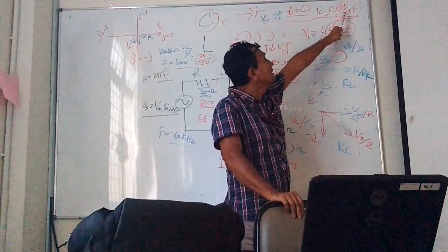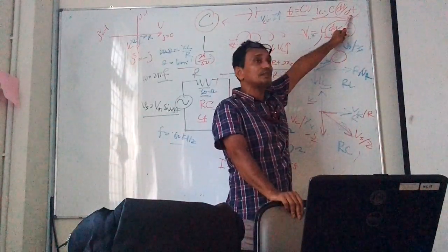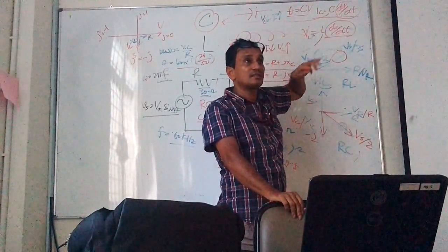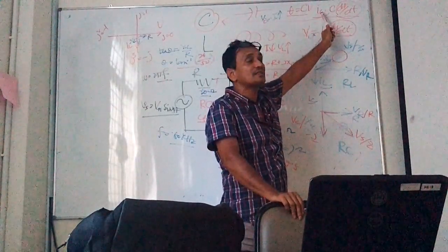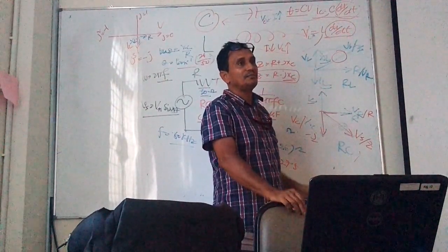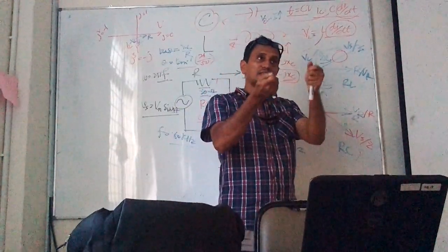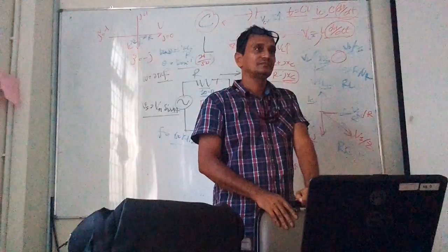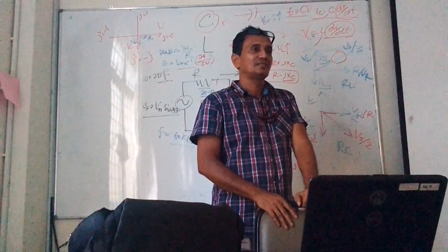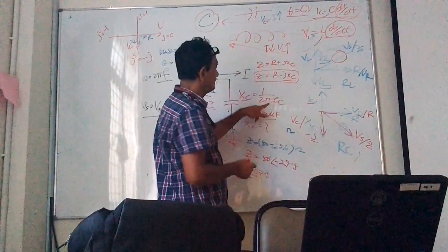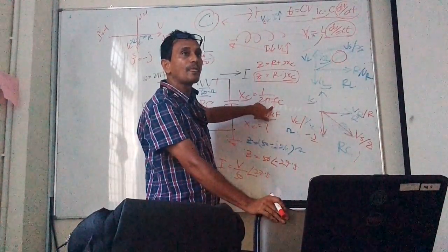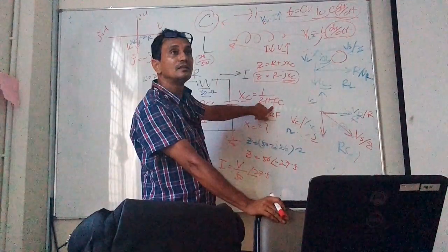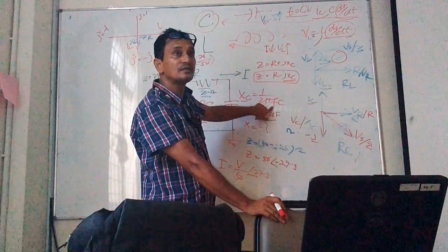If there is a DC voltage, is there any change with time? No, definitely no change in time. There is steady voltage. So what value should the capacitor current IC be? If you set up a DC circuit with a capacitor, what should the capacitor current be? The frequency for DC is 0.